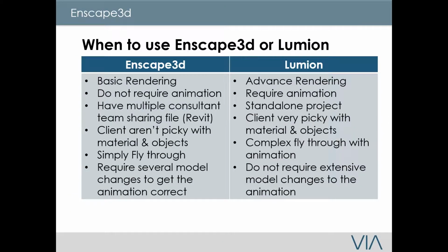Now, when to use Enscape or Lumion? Okay, this is what I typically tell users: if you have to do basic rendering, you don't require any animations, and you have multiple consultants working with you, let's say they're using Revit, I would pick Enscape. And if the clients are not picky with material and objects and you want to do a simple fly-through, then I would say use Enscape.